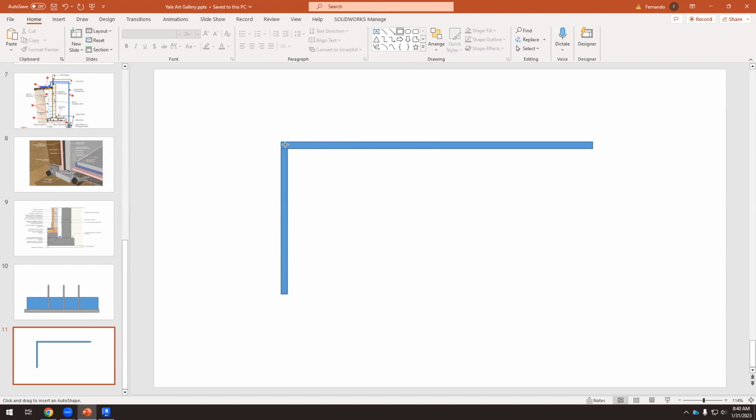Okay, so what is mine is the lot that is within this wall. And this is another property. So this piece of land is not mine, and the other one is not mine. So in that case, we will have to use a footing that is not centered.